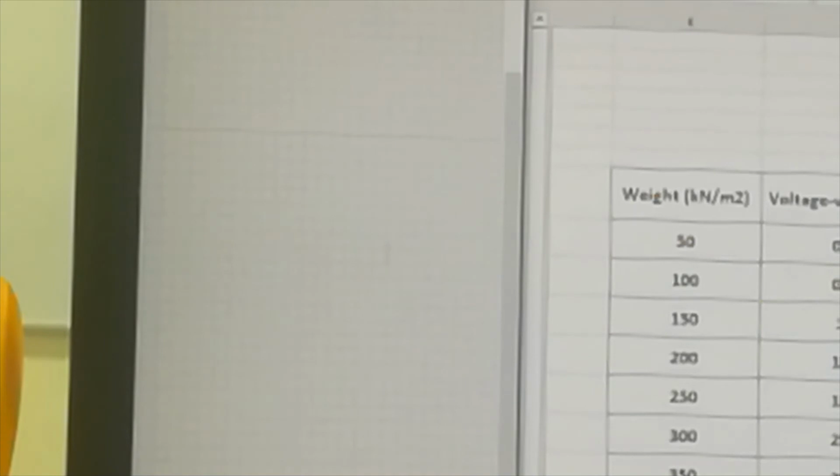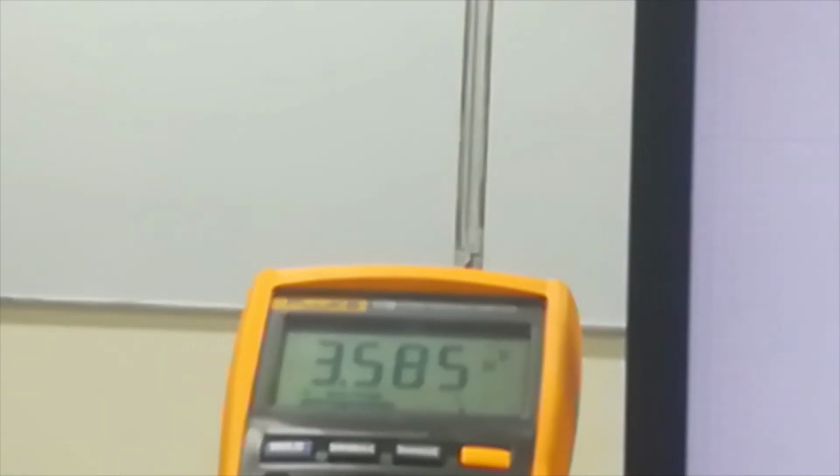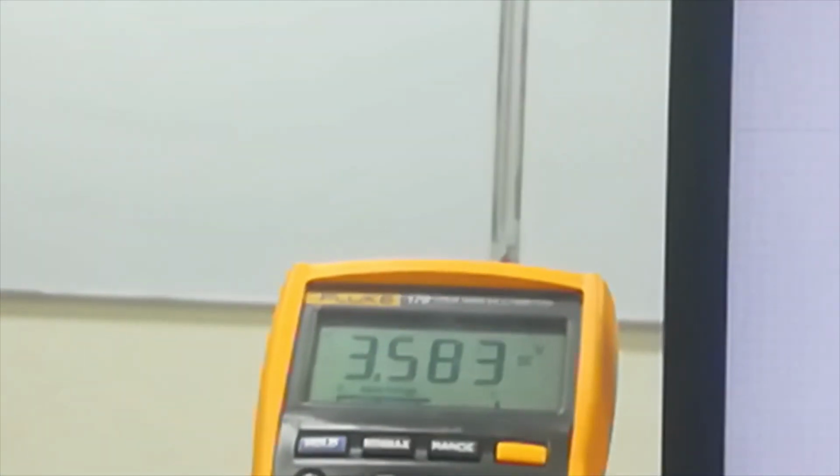Then, as we said from the beginning, the values coming from the data acquisition card and the values coming from the voltmeter are very close to each other. However, one of the sources of error is that we now have high pressure of oil inside this tank, and with time the pressure inside the tank is relieving. Also we have some oil leakage from the tank, which decreases the pressure with time.